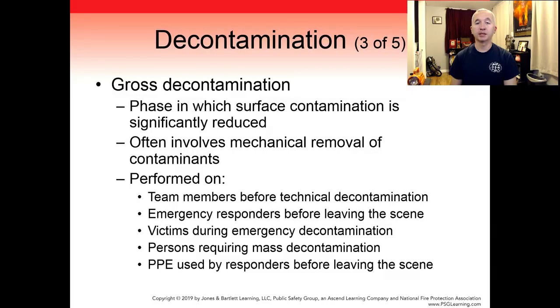Gross decontamination is a phase of the decontamination process where significant reduction of the amount of surface contamination takes place as soon as possible, most often accompanied by the mechanical removal of the contaminant or initial rinsing from handheld hose lines, emergency showers, or other nearby sources of water. It is performed on team members before their technical decontamination can take place, emergency responders before leaving the incident scene, victims during emergency decontamination, and persons requiring massive decontamination. PPE used by emergency responders before leaving the scene,